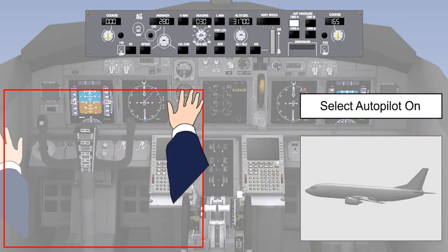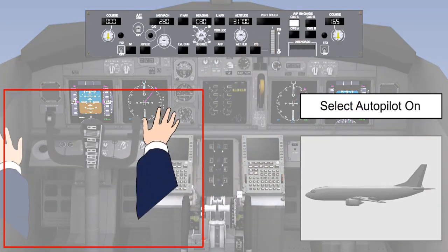When the autopilot is engaged, it has to be capable of continually trimming the aircraft in pitch to account for variations of the centre of gravity, configuration and speed. If this did not happen, out of trim forces would be felt on the servo motor, and at the point of autopilot disengagement, a pitch input would occur, causing the control column to be snatched or jerked.